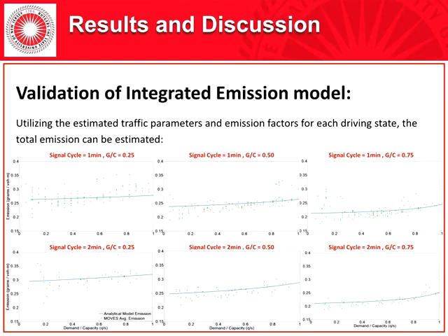Finally, here are the results of emission estimations. The continuous green line represents the results of the integrated traffic emission model, which provides a smooth and continuous emission estimation. The green dots are the estimated emission directly calculated by the microscopic emission model of MOVES. Any error in the estimated number of stops or duration of idling or cruising can directly affect the resulting emission estimation.